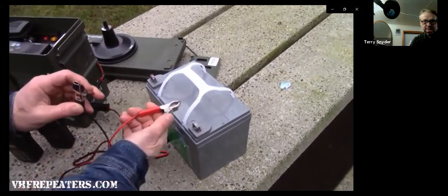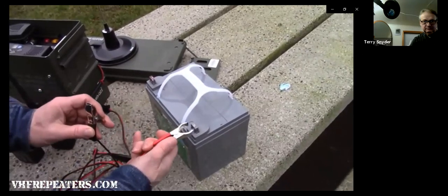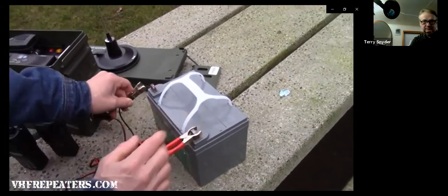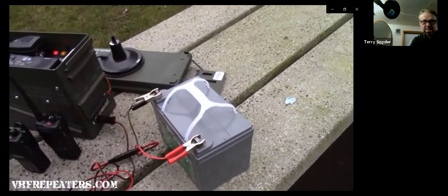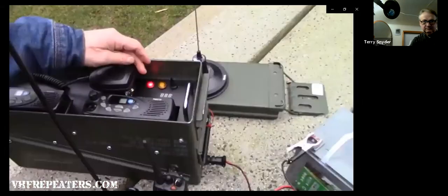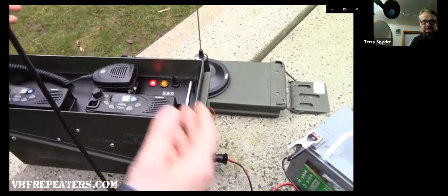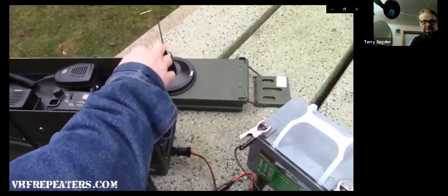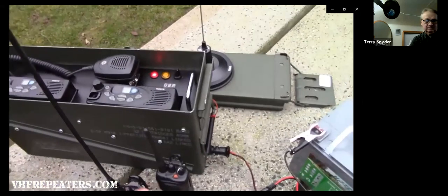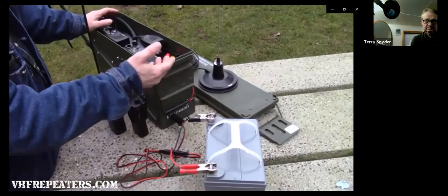We're going to take the positive side of our wire and connect it to the negative side of the battery, and the negative side of the wire to the positive side of the battery. We have our indicator that's just come on the repeater, indicating that we have a polarity problem. But the best part of this is that we can actually turn our power on, and nothing happens to the repeater, thanks to the Texas Instruments module that protects us against reverse polarity.